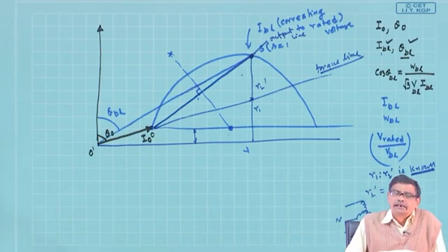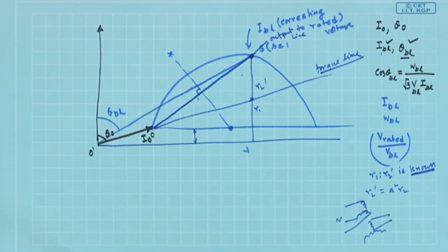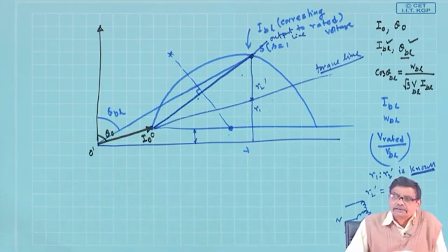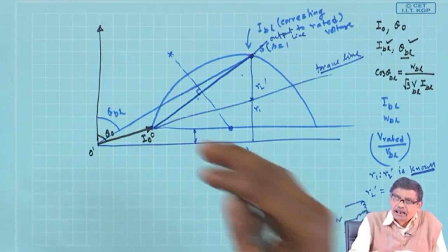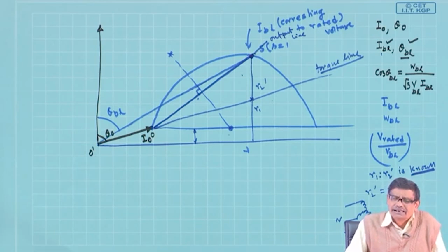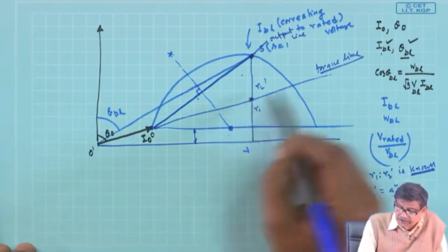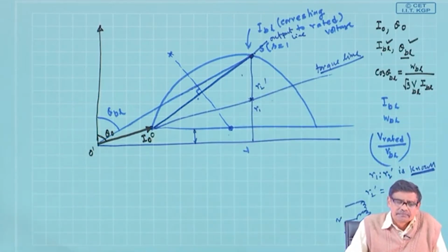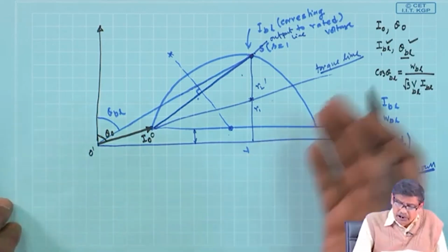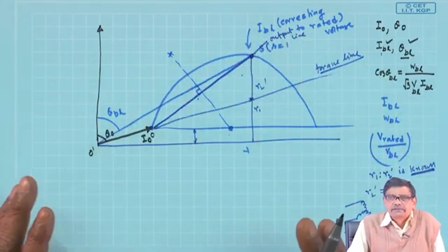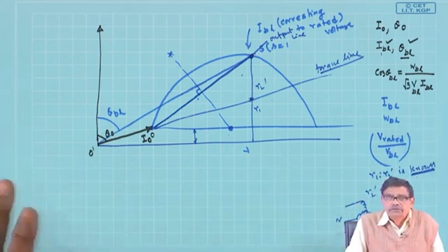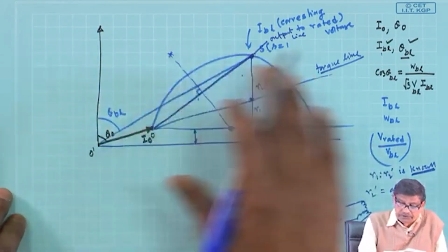Another way of estimating R2 dash, I am telling, if it is a cage rotor, you first find out R1, okay? Then apply some AC voltage instead of DC, then R2 dash will appear, and from that equivalent circuit, it will not be that easy, only R1, R2 dash, some leakage reactance will be there, because R1, R2 dash after all are small quantities. So it can be by some rules perhaps separated, R1 is to R2 dash, and if it is separated, then only I can draw the torque line. In absence of any data, assume 50-50, 1:1. These are all estimates, nothing very accurate, no, never, but it is a very simple means of doing these things.